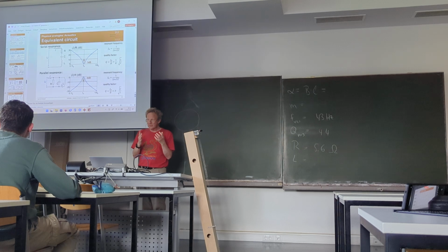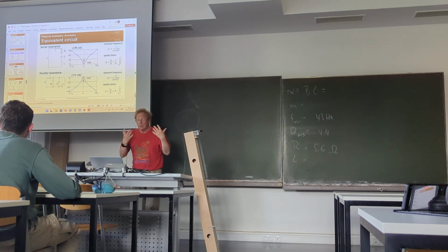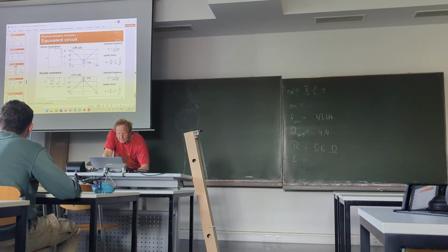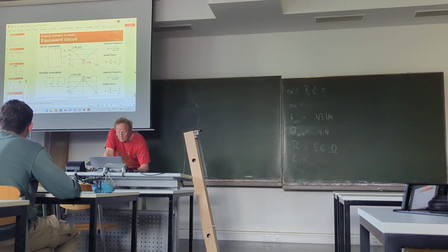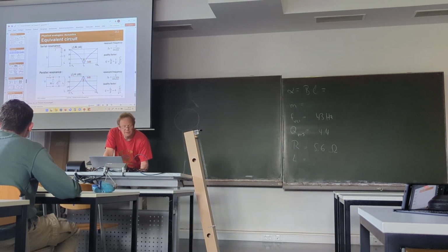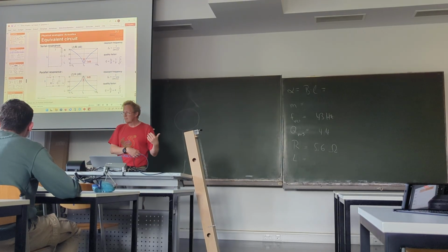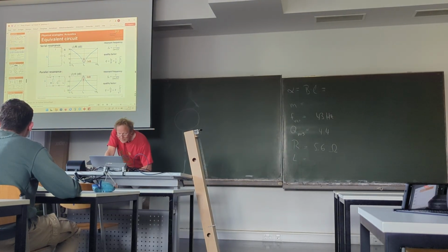So both elements together are something like an interruption. So the only thing that remains then is the resistor, and that is the maximum value. For lower frequencies or for higher frequencies, either the capacitor or the inductivity will be a good conductor, so we have lower impedance, but for the resonance we have a maximum, which is defined just by this R.